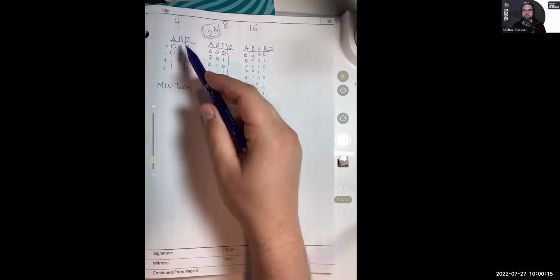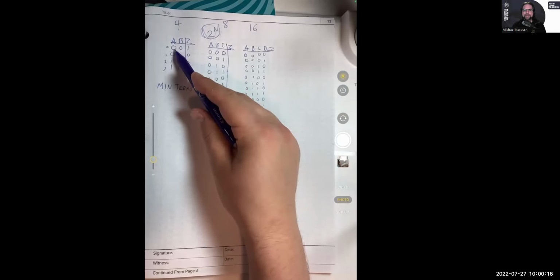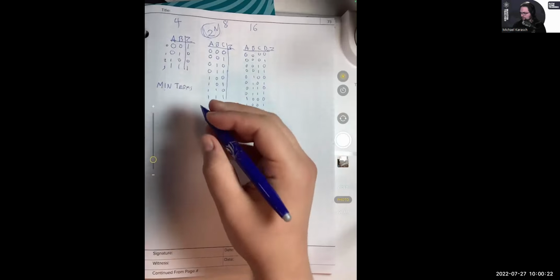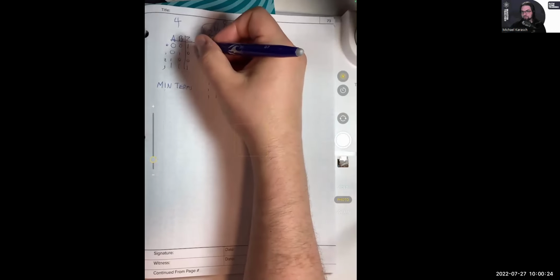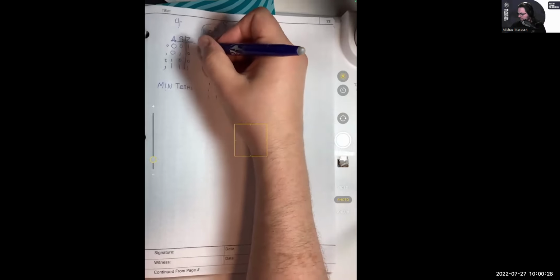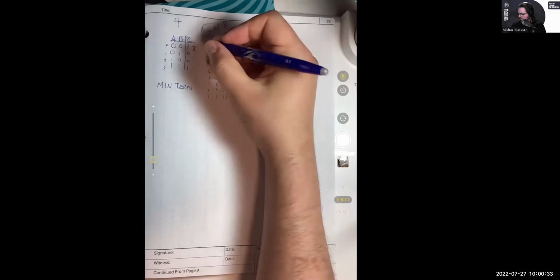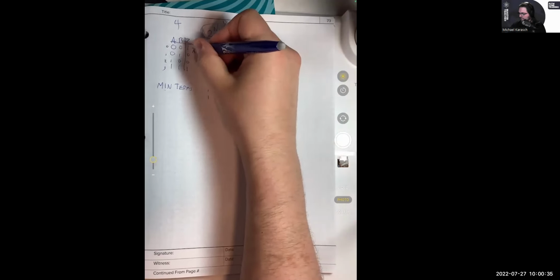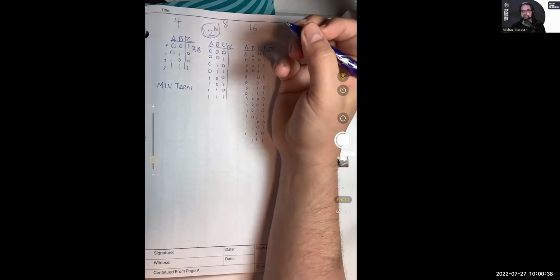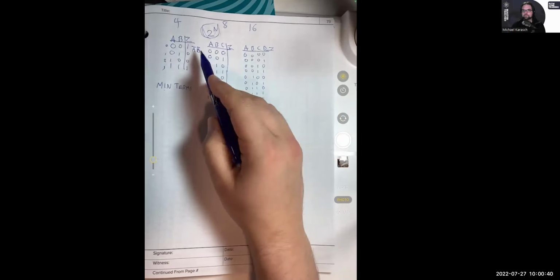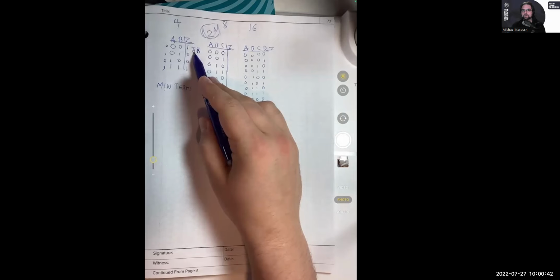Ooh, and. So really it's not A and not B. If we recall, and is multiplying, and not, we put a bar over it. So this would be not A and not B. Not A, a bar over it, and, so multiplied, not B.